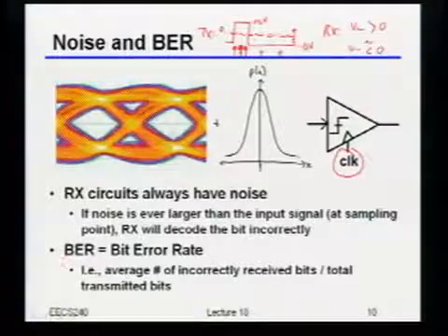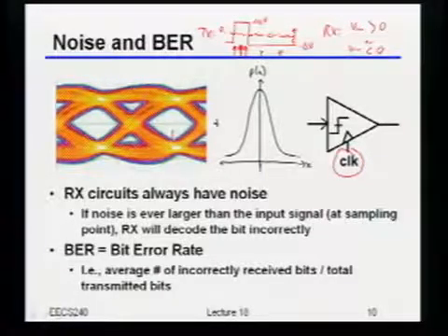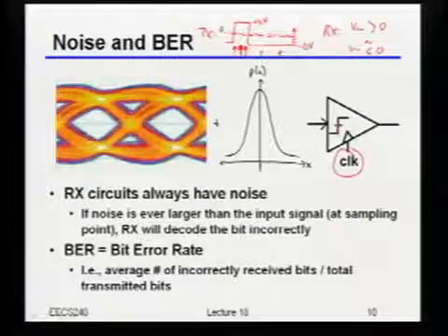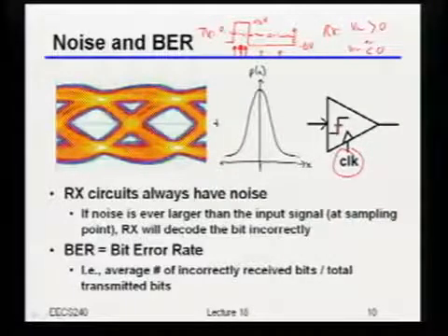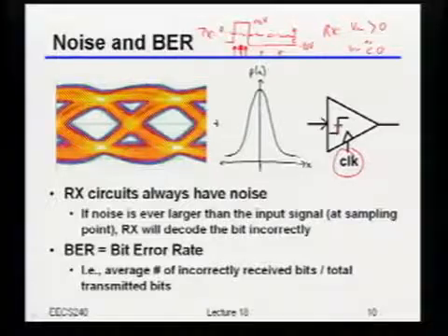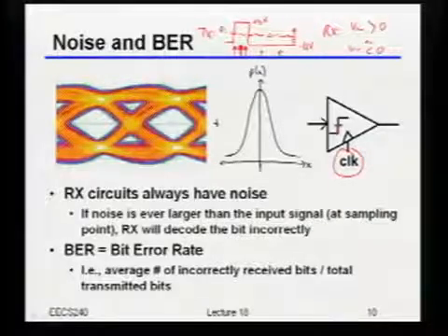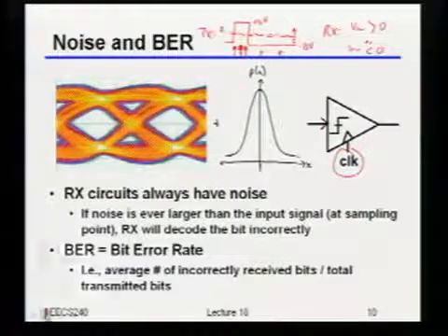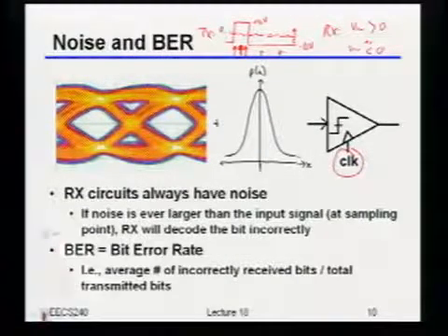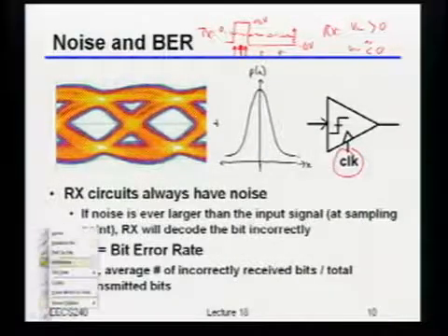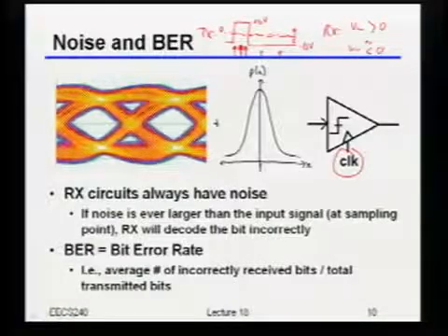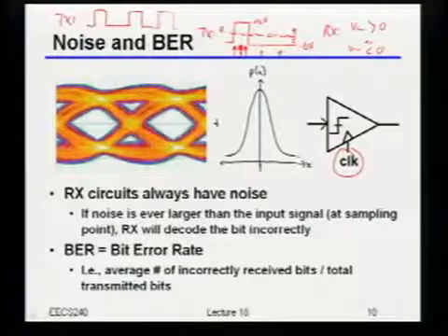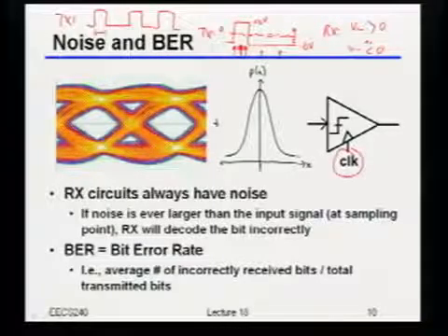In order to understand how bad or how good this receiver has to be, the way we usually like to take a look at that is to look at what's called the eye diagram. Okay? All this eye diagram, which is shown right here, is doing is, let's say I look at the transmitted bits, so let's say I had something that looked like this, where each one of these is a bit time.